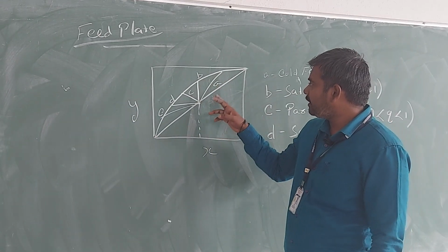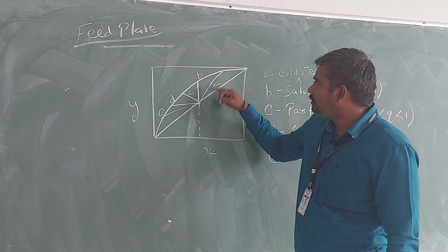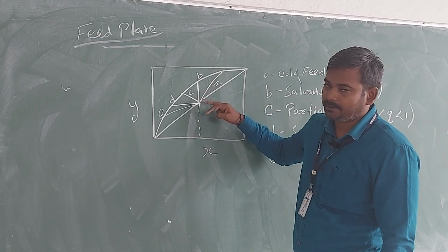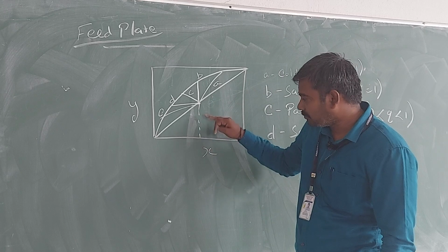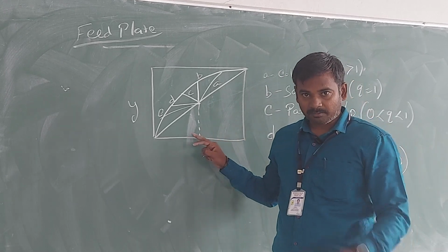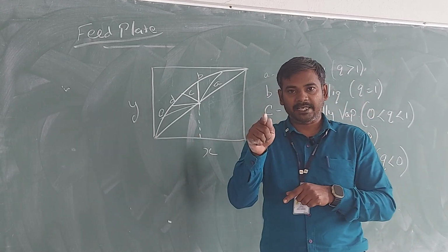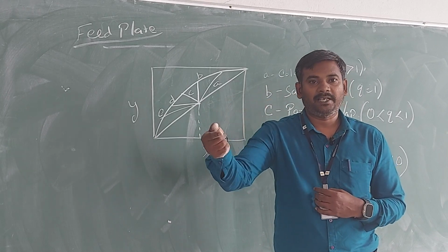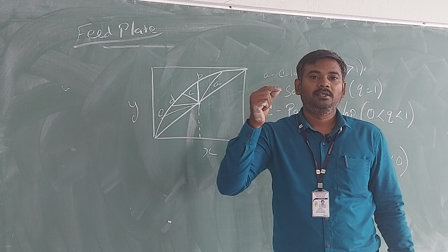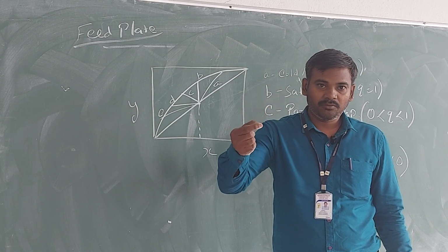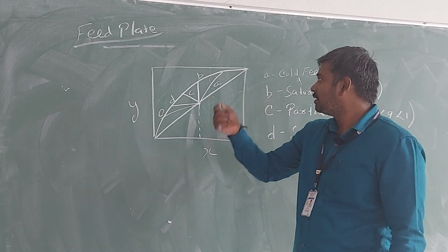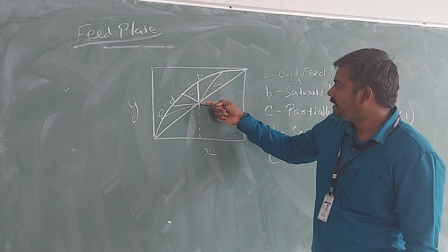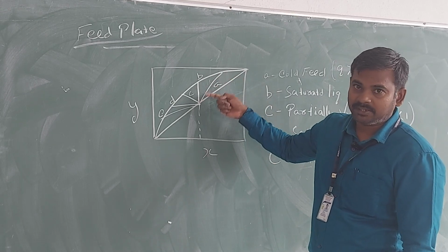If you have a cold fluid, the intercept will be like this only. From the XF, you are going to draw the feed line, stating what the condition of your feed line is. If the question gives the condition of Q as cold fluid, your intercept will be like this only, in this manner.